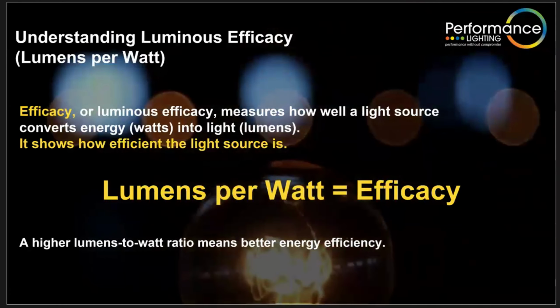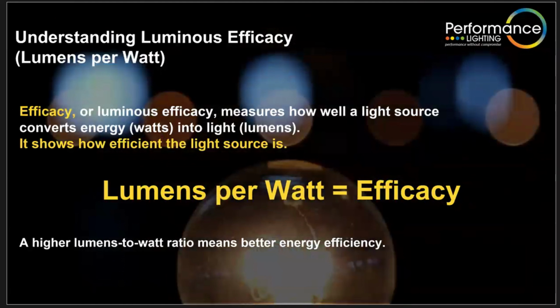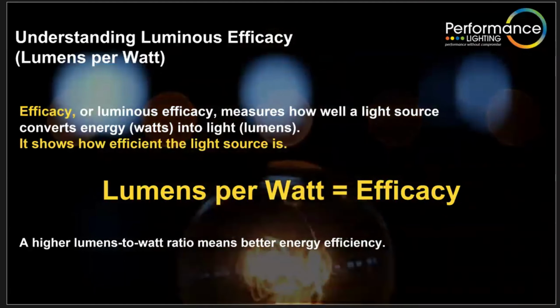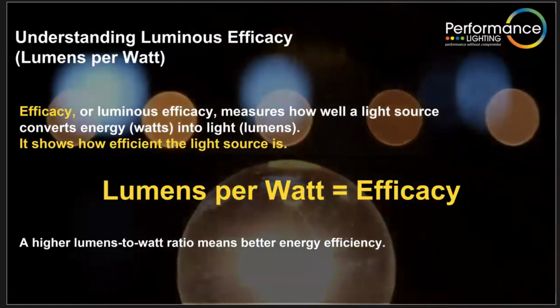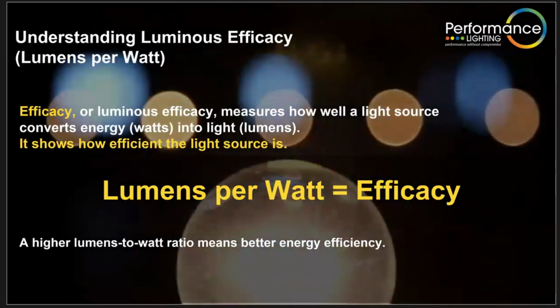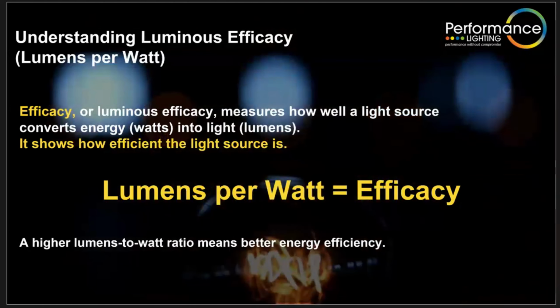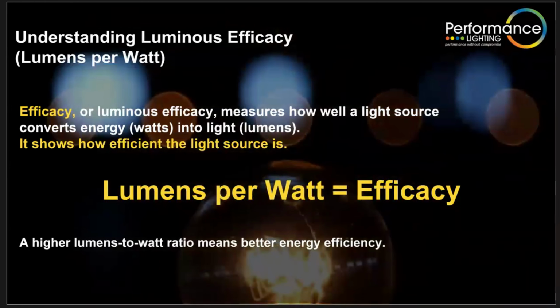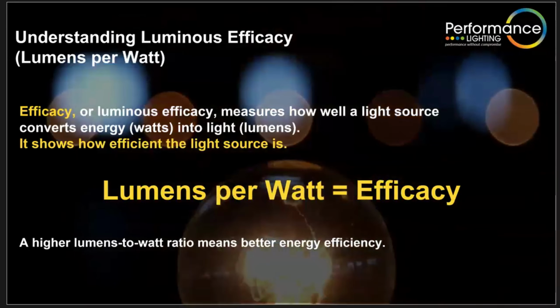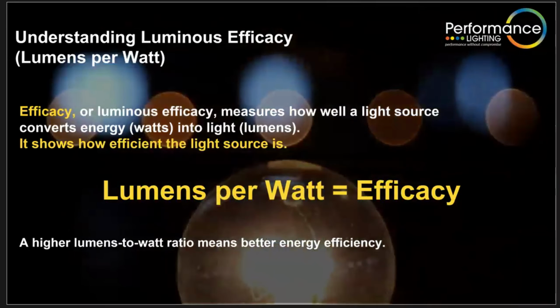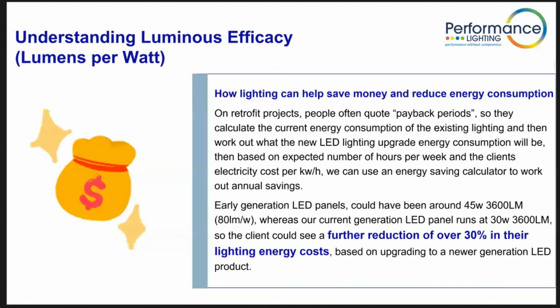As a lighting manufacturer, we'll quite often get asked for, a good example is a 200 watt LED high bay, and people won't ask what the lumen output is, they just want a 200 watt high bay. Some 200 watt LED high bays are circa 20,000 lumens, so 100 lumens per watt. But then we could have a 150 watt LED high bay that is 24,000 lumens, so it's actually brighter than the 200 watt and using less energy. So that's about the efficacy or efficiency of the LED.